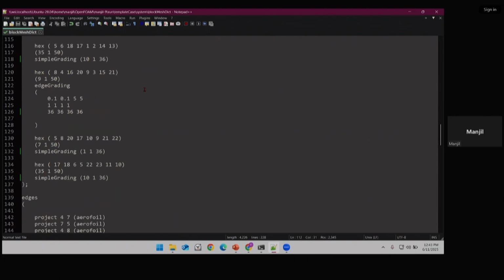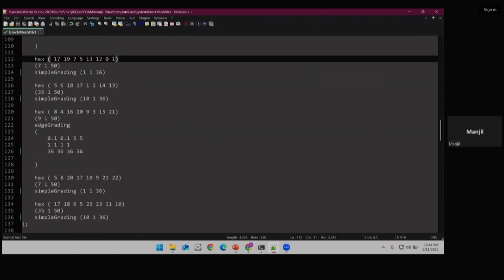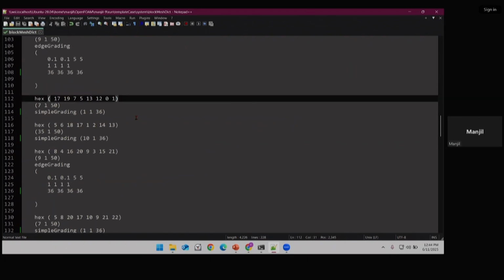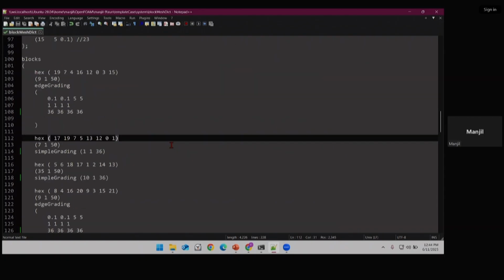Actually y plus equal to 300 is a very large y plus. It's always recommended to use the range 30 to 100 for the high Re formulation, or if we want to resolve the viscous layer properly, then y plus equals to 1. But right now we are doing 300 because the number of cells will decrease, and this will also take less simulation time, and the cases will run faster for our case. After we have done this, I think our block mesh is ready.